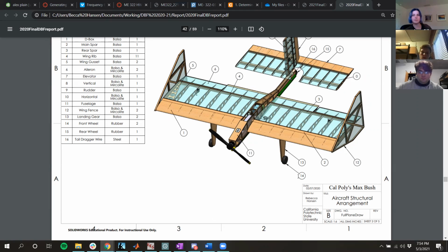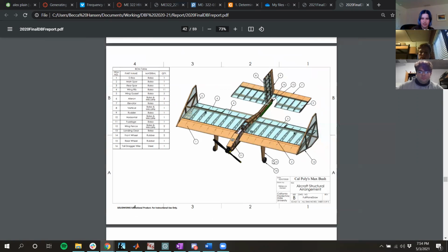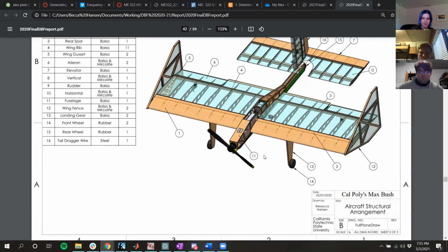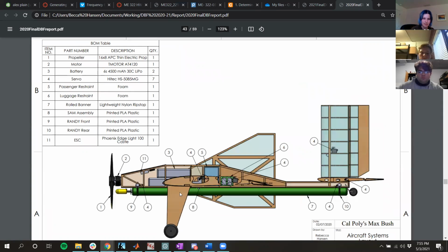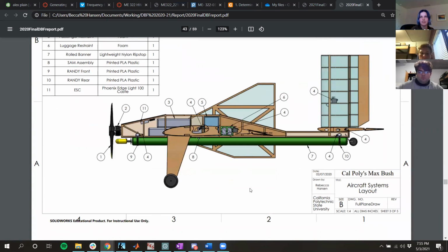So you're totally right about damping. Because we don't have the complexity to put shocks on it, you can throw that into the tire, and that'll decrease the impulse force, so your legs won't break and you won't transmit a big force through the rest of your structures. So yeah, thicker tires are good. Some people will say something about aero, but whatever.